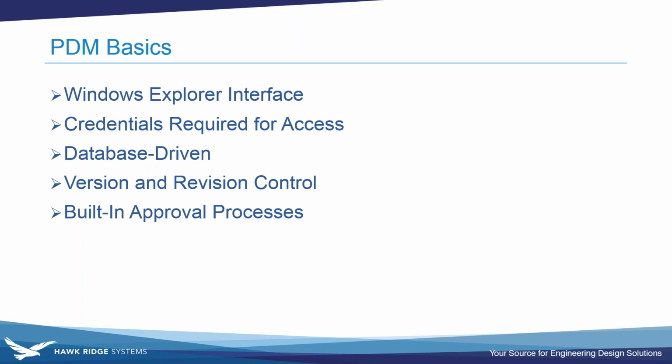And then we can build those approval processes into the PDM interface. So if you have existing engineering approval processes, or maybe engineering change order, engineering change notice processes, those can be built into this system. So if you were previously moving a file or a printout of a drawing from one person's desk to the next person, doing physical sign-offs, hopefully some of that can be reduced by what can be built into this PDM system.